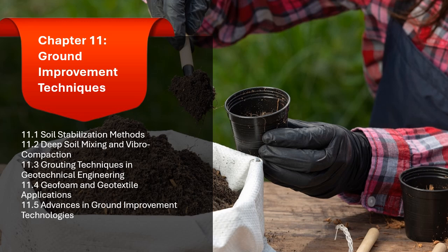11.2.3 Comparison of deep soil mixing and vibrocompaction. Feature: deep soil mixing, DSM; vibrocompaction. Soil types. DSM is effective for cohesive soils, clays, silts, and granular soils.